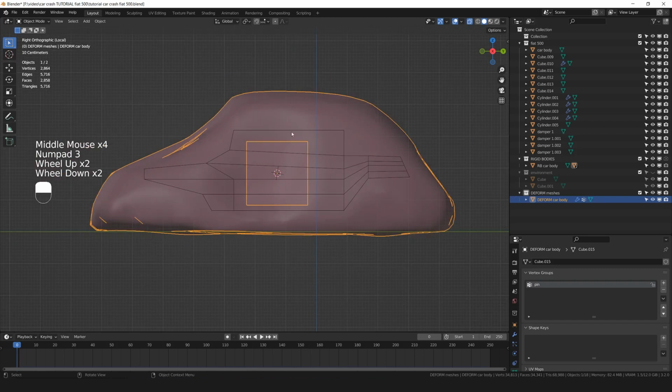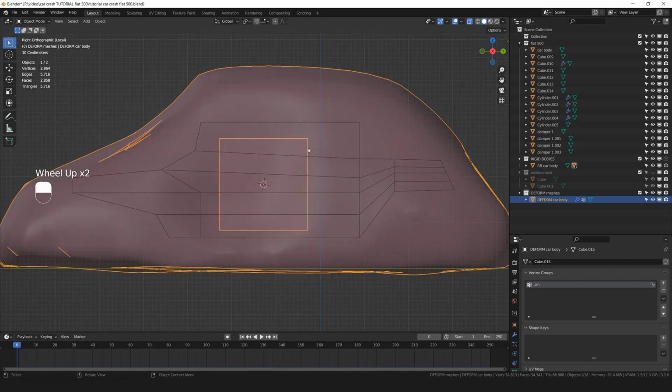This internal part should represent more or less the shape of the rigid body, but has to be a little bit smaller compared to the rigid body, because this internal part is gonna be stiff. If it's bigger than the rigid body, it's gonna create glitches when the rigid body is gonna collide with the ground and the floor, and instead, if it's gonna be smaller than the rigid body, it's gonna be perfect.